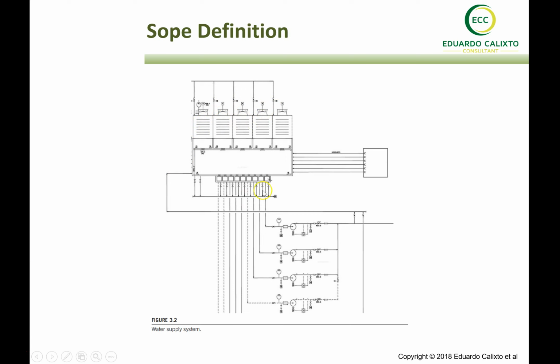We are also considering the valves between the water storage parts and the pumps, and in the pumps we'll consider some sensors here, if there are some controls, and also the pump by itself, and the additional valves after the pumps. So that's very important information that needs to be confirmed. We need to be aware that if we are in the design phase, maybe during the design this PID will be updated, and we need to update our run analysis accordingly.